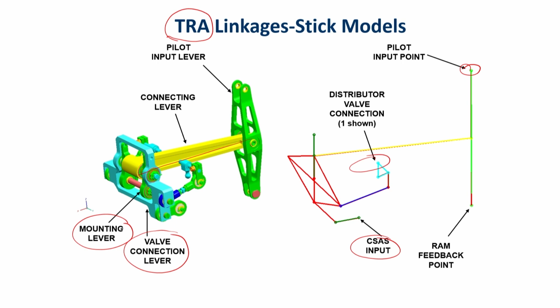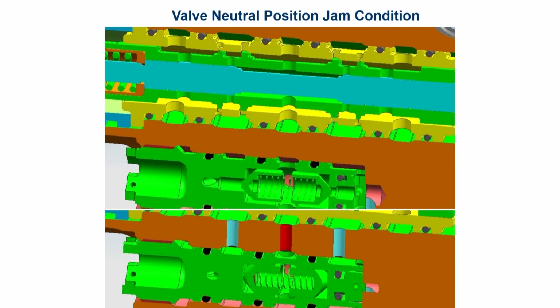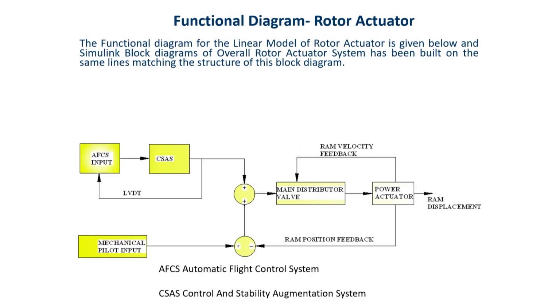Sometimes we also keep a computerized system, which can take care of something like a fly-by-wire type of system, which can take care of the system without even the pilot in certain places where it is not so critical. And this is what you see, what is actually happening inside a hydraulic network. You can see that there is a small orifice here, and this block here can actually travel both ways, and this traveling, I told you, is the spool valve's movement that will allow the hydraulic fluid to come and apply the force. So, that is taken care of.